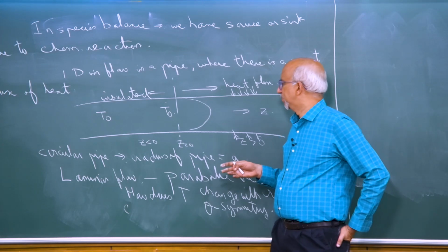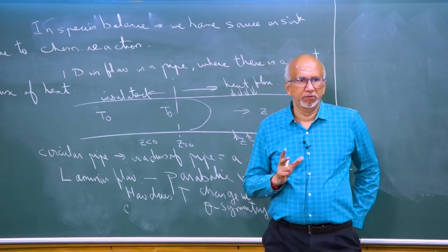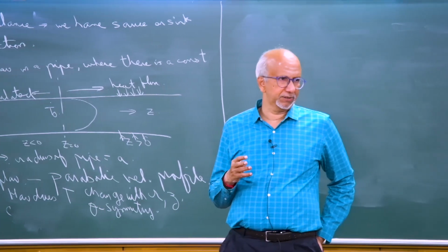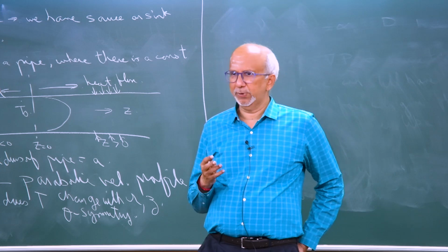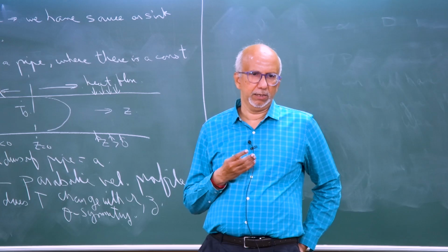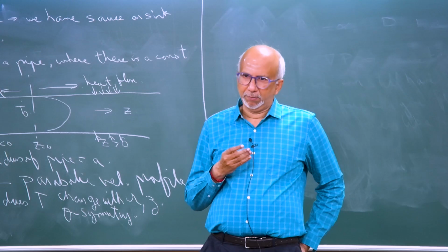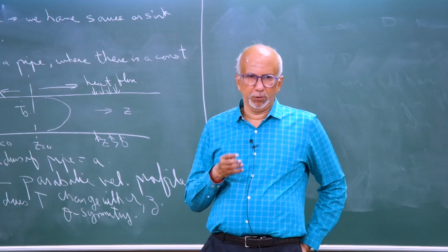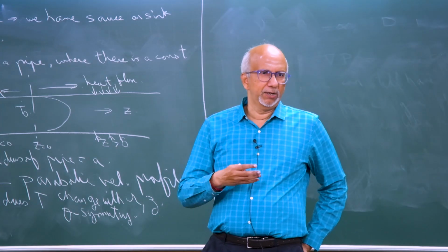And when we derived this laminar flow velocity profile, we had assumed viscosity was constant, and then we did the calculation and got the profile. So, clearly the first question is, can I even use the laminar flow velocity profile? Because I have to go back and re-derive my velocity profile by including viscosity as a function of temperature. So, this whole concept of fully developed flow is not even valid.